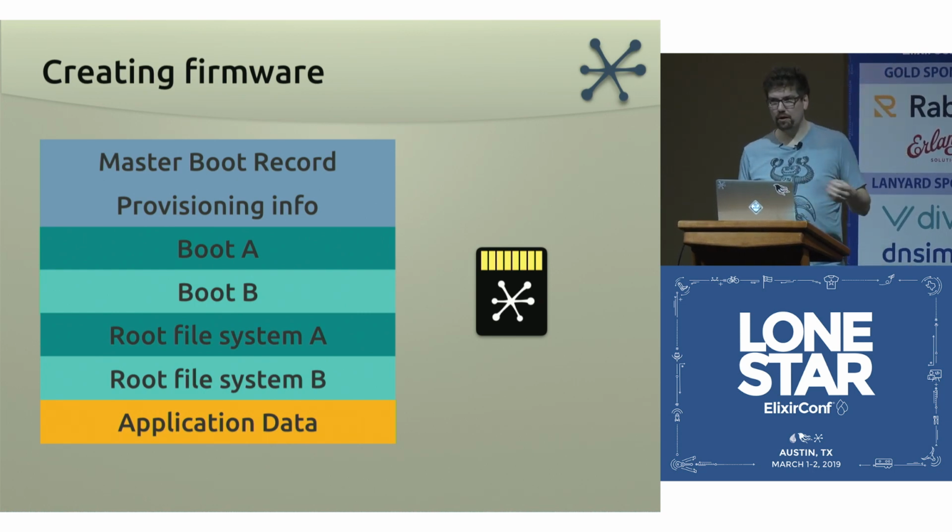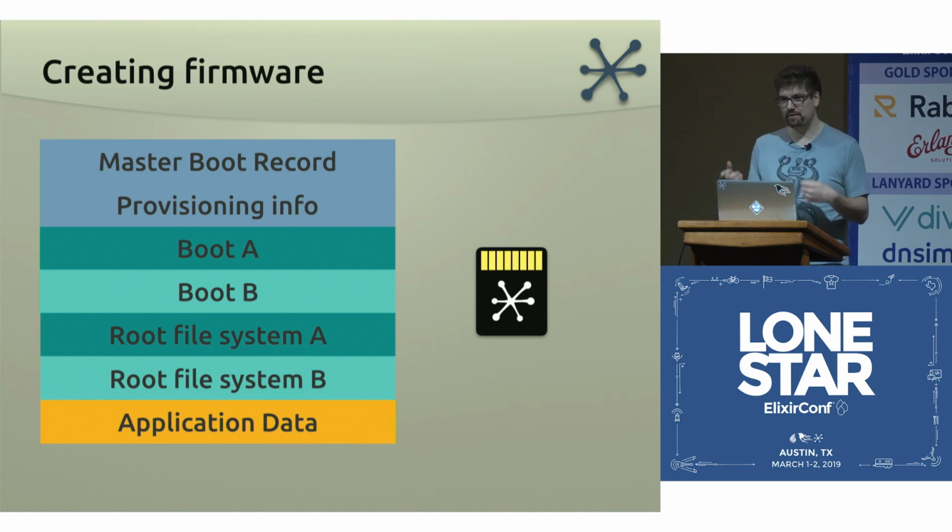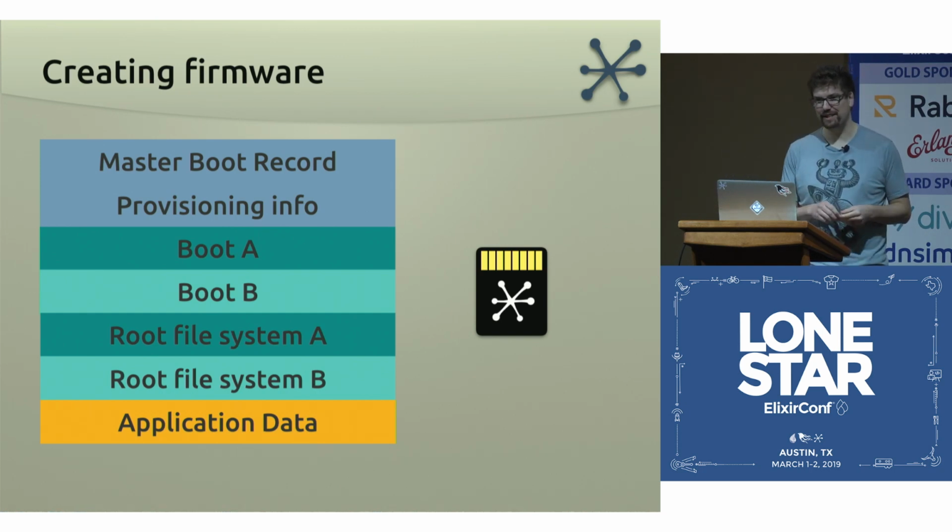And so, we all are familiar with, well, maybe the concepts of immutability in Elixir, and the kind of guarantees and safety that provides us. And this is just a way to extend that feeling of immutability and safety to the runtime. This is important for situations like tiny machines where you never know, the user is just going to expect that you can pull the power out at any moment, and then it's just going to power down, not gracefully all the time. So having that mounted as read-only is going to prevent corruption cases.